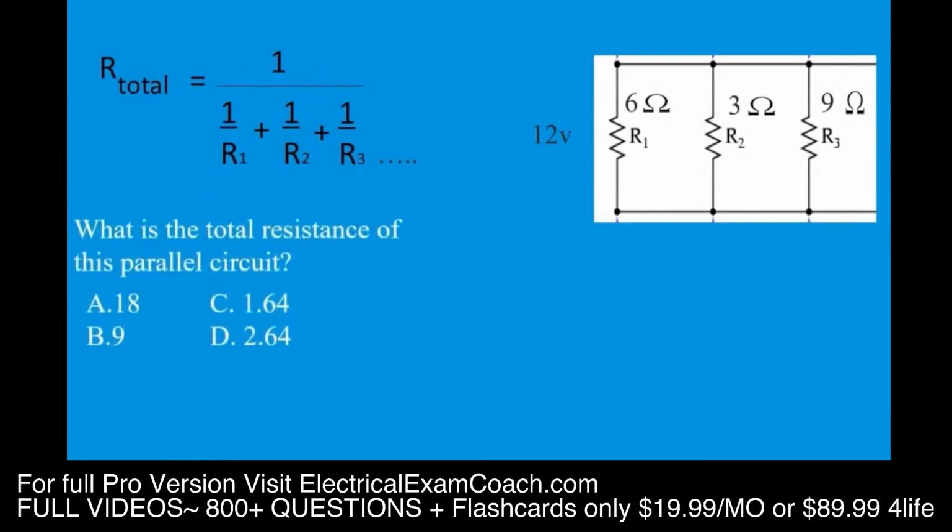So what is the total resistance of this parallel circuit? I want to note right away that we have 4 options here in our question. The answer is always going to be smaller than the smallest resistor in the circuit. So if you're in your testing center and you get a question like this, we can tell right away that